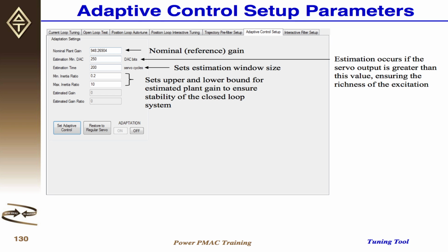Adaptive controllers are nonlinear controllers, and sometimes, let's say you try to come up with the mass of the robot. The algorithm will run well, but then one of the parameters will start drifting, especially if you don't have a rich signal, meaning you're not exciting the system well enough for your estimation to work. The parameter will drift, and after a while it's going to run away and go unstable.